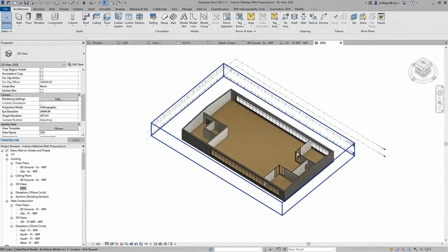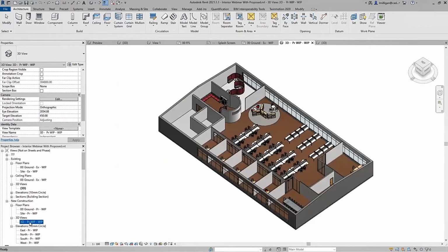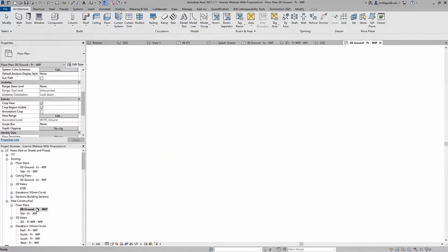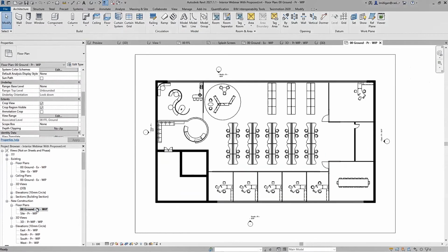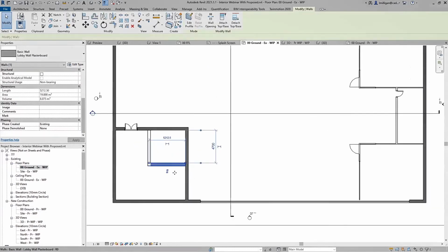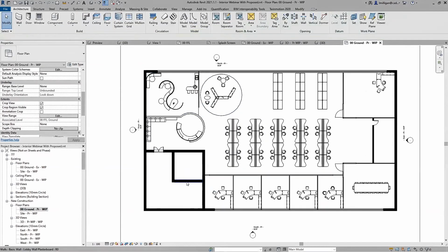Also in my plan view, I've got my existing. Now if I move something in existing, it will update in proposed because I'm moving something in the past. And this object is an existing object. Now, if I delete something which was created in the proposed, i.e. the new, that doesn't update in the existing because it hasn't happened yet. So again, a little bit confusing, like we are time traveling.